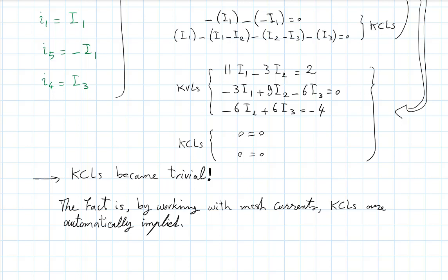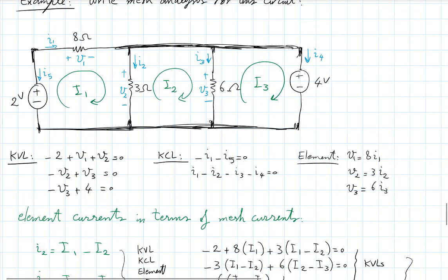And so if you look at the system of equations we came up with, that's 3 equations, 3 unknowns. Those are the mesh currents, and relatively simple to solve. Now, of course, you can come up with a bigger example where you have not only, like we had here, some independent voltage sources, but you could also have independent current sources. You could also have dependent voltage or current sources. And so you would have to deal with that in very much the same manner as we did in the big nodal analysis example we just solved. And we will do examples of that next time. But the essence is this. And of course, then you can arrange these in a systematic way in a matrix form, and so on. But this is really the core in terms of the general approach to mesh analysis. This is what it is.